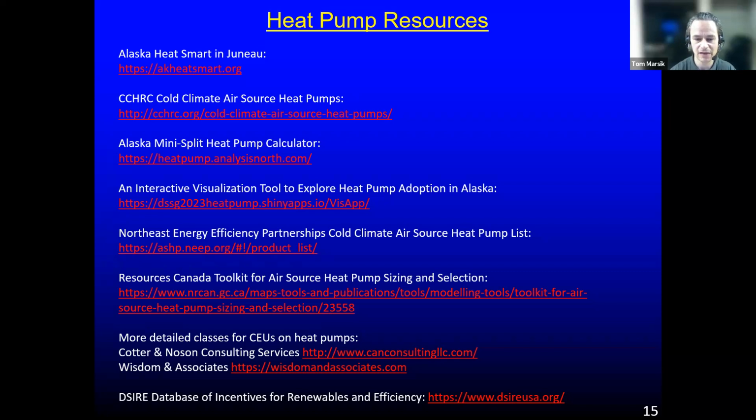So if you have, say, an oil-fired boiler in the building, and now you decide to also install a ductless mini-split heat pump in your building, so during those temperatures, when the ductless heat pump is able to operate and it's supplying heat into your building, it's lowering the amount of heat that your oil-fired heating system is supplying, which means you are burning less oil.